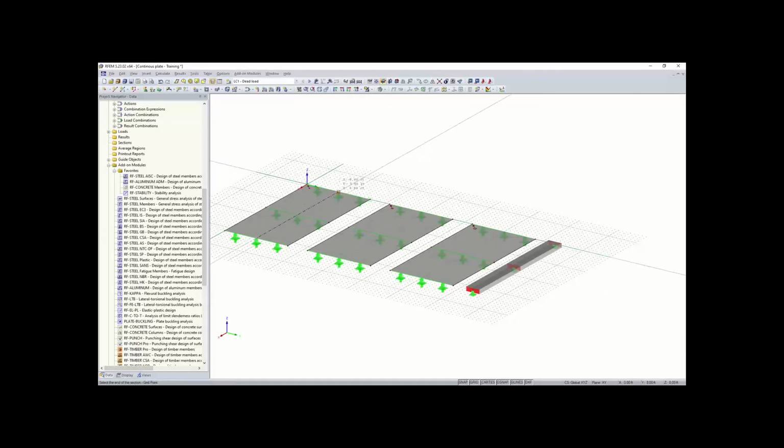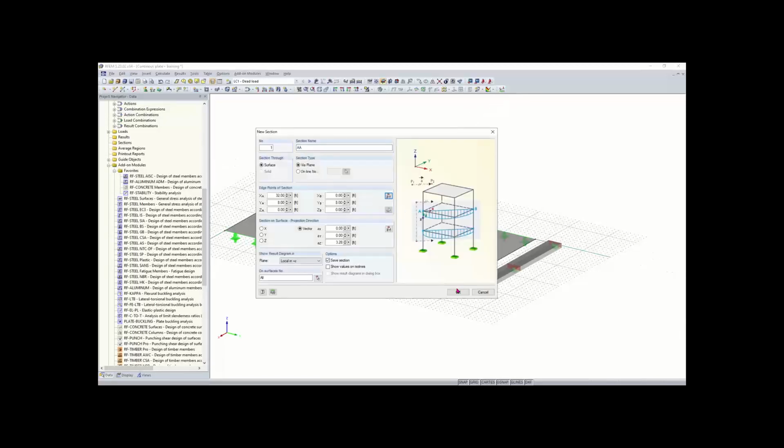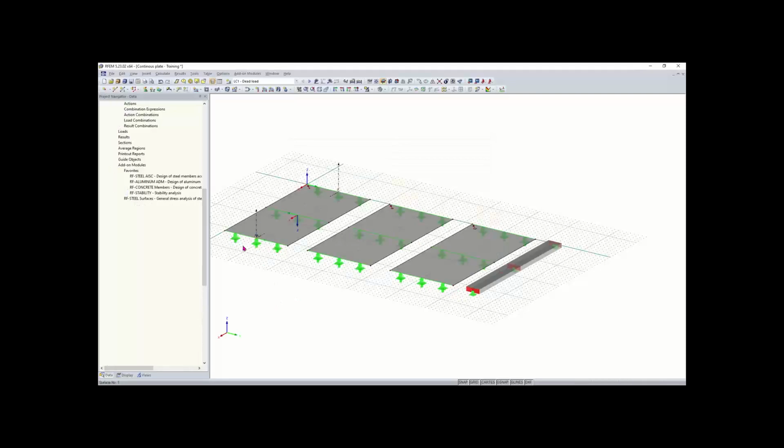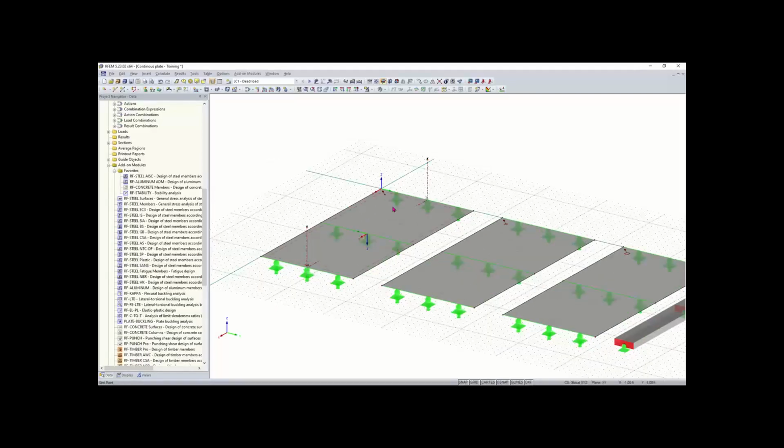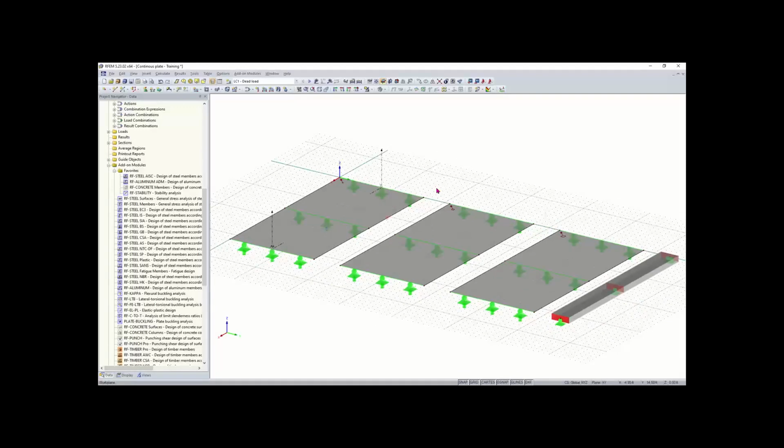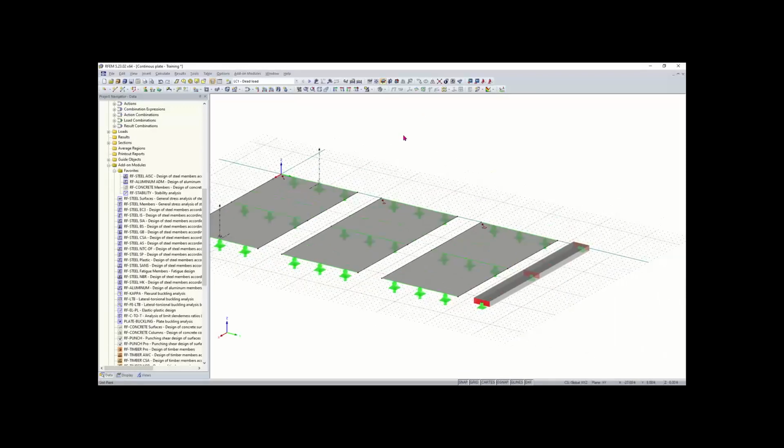And you can see that there's an icon here, kind of like in AutoCAD, where you can select the midpoint of your line, and then you can do the same thing for the other line. So now that section cut, everything is good and defined. It's going through our local Z plane here in the positive direction. We have a surface selected here via plane, so this is all defined. We can click OK. And now you can see that that section cut has been defined there. And you'll see that these will come in handy for our results.